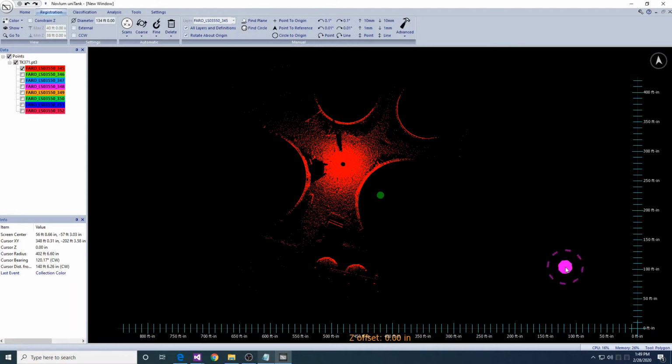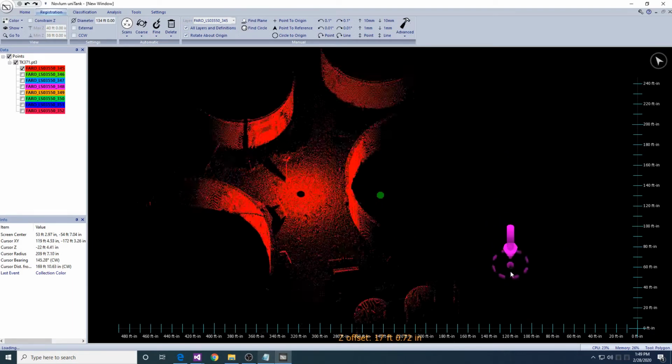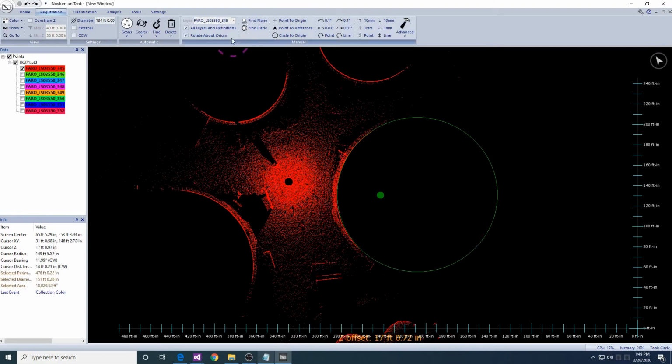If all else fails, you can do manual registration by registering one layer to another, one at a time. This process is the most time-consuming, but also the most robust, because it ensures you have sufficient fiducials between layers before moving on.